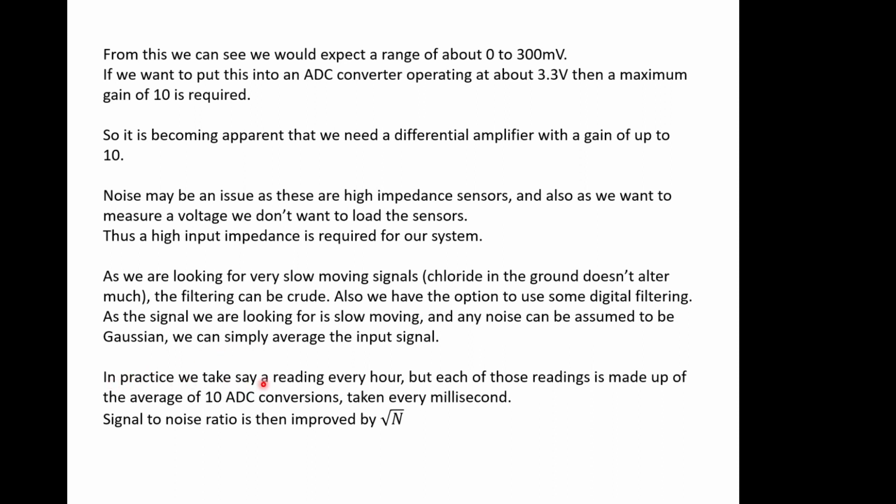Right, so in practice, if we take a reading every hour, but each of those readings is made up of the average of 10 ADC conversions, we improve the signal to noise ratio.